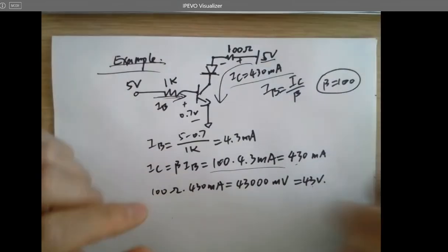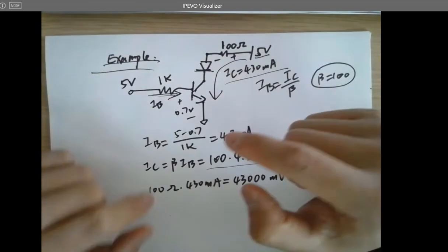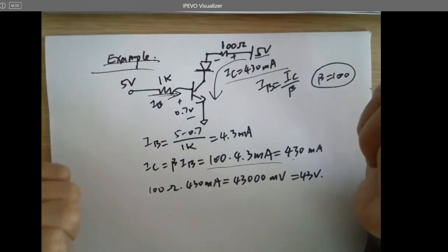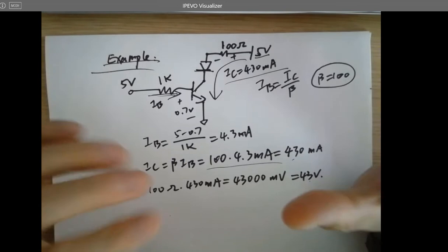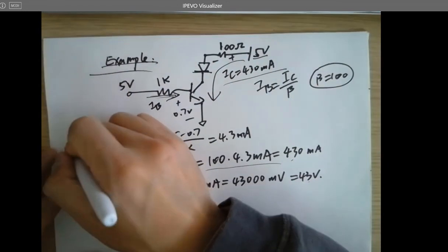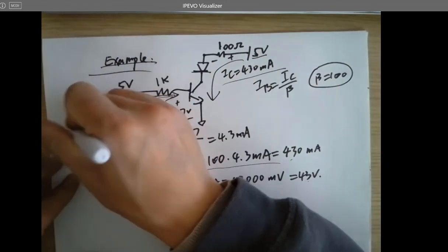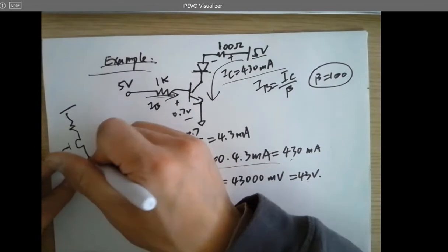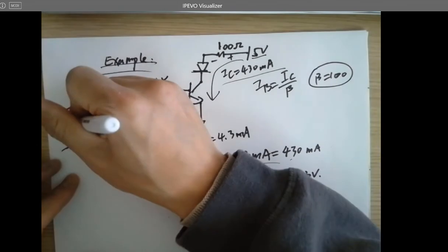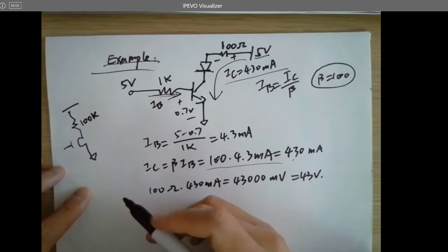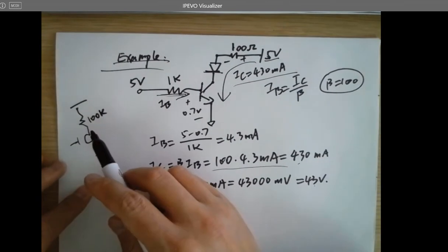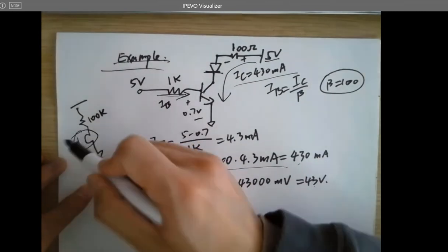We do the similar calculation for the NMOS as well. We just assume whenever you have a huge resistor on the top, like 100K, you want to be careful. Whenever you see this, possibly this is not being in the saturation mode.